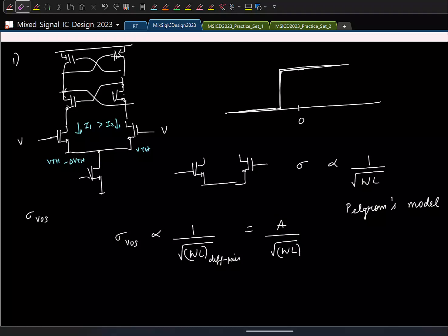And I think I cross coupled it wrongly. Yeah. And these simulations are called Monte Carlo simulations. Have you heard of Monte Carlo somewhere? Okay. Basically, any kind of analysis or simulation that includes statistical randomness is called Monte Carlo. So here the randomness is basically the mismatch in these devices. So you run a Monte Carlo simulation.